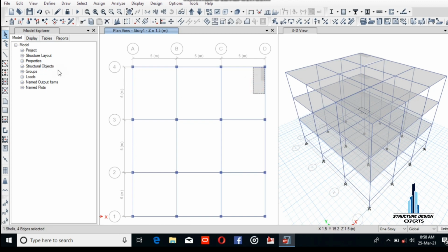That is the way how to delete. So click here and go to design, edit and delete. So I delete this small piece also. Don't select the beam, I select the slab and go to edit and delete the slab section. So it has been deleted. This is the way how to delete. Go to the first story. Now we are in the first story. You see that z is equal to 5.7. It means that we are in the first story.